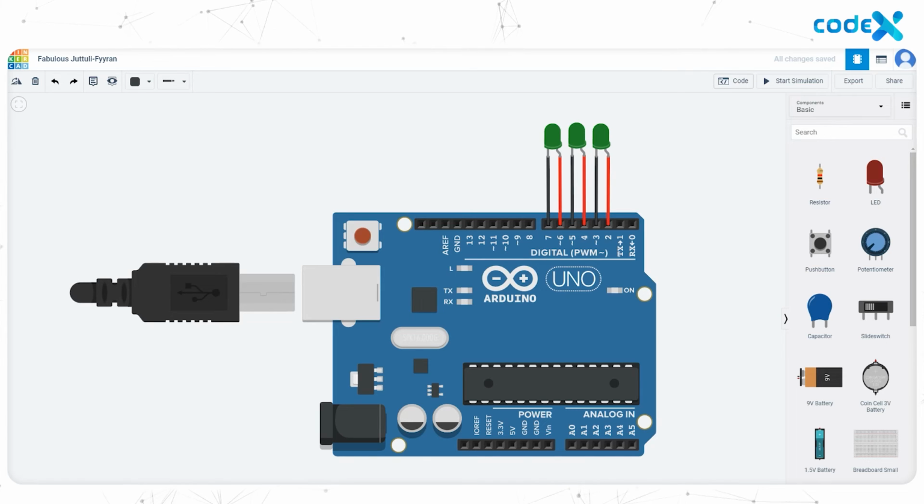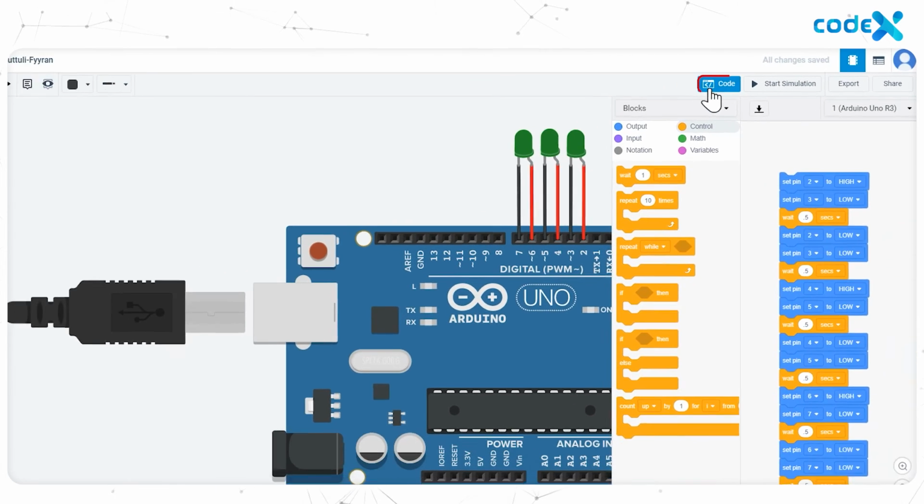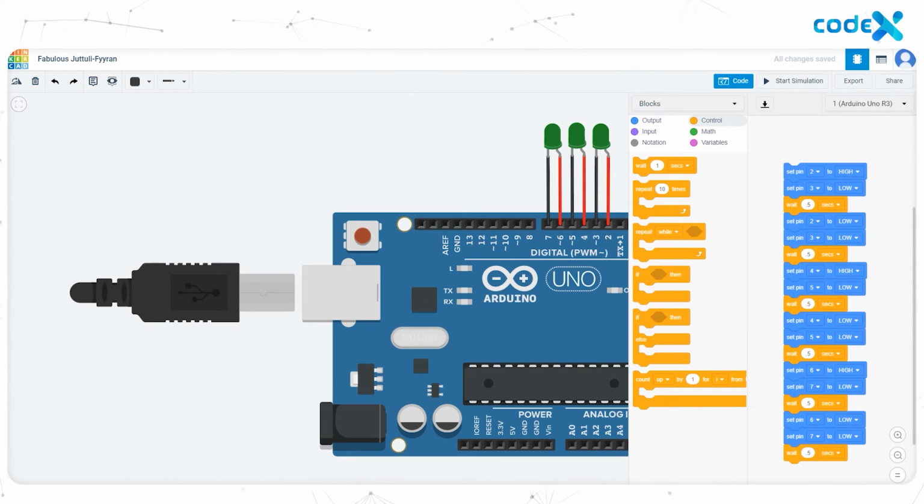Isn't it simple to create patterns for the LED blinking? Just remember one thing. All you need is to set the codes according to our desired pattern and let the show begin. Let me show you an example of a different pattern. Go to Codes, set pin D2 to high and D3 to low, so that LED 1 will turn on.